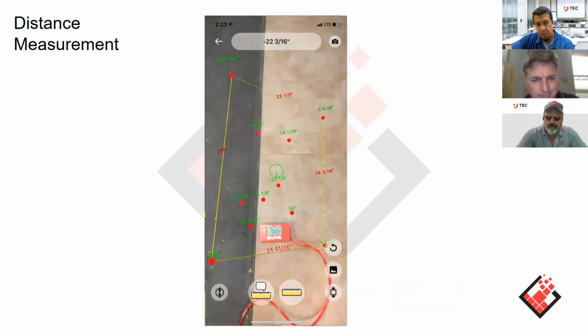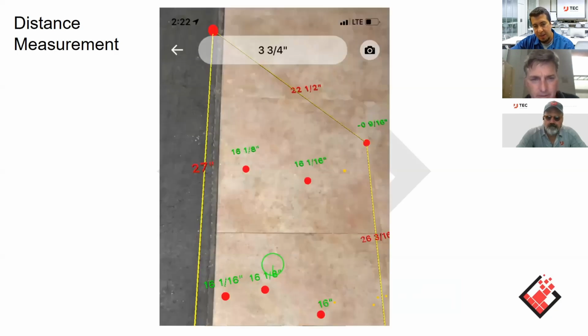So what you'll do, you'll tap that one time, and then you'll just tap that ruler, and every time you tap that ruler, you'll see that we have green measurements on the inside of that perimeter. Those are all height elevation marks within that perimeter, right? So again, you can take as few as you need for your job site. Maybe you just need 1 point from high to low ground, so you would have 2 elevation points. Maybe you need 0. That's more based on your job site and what you're looking to do.